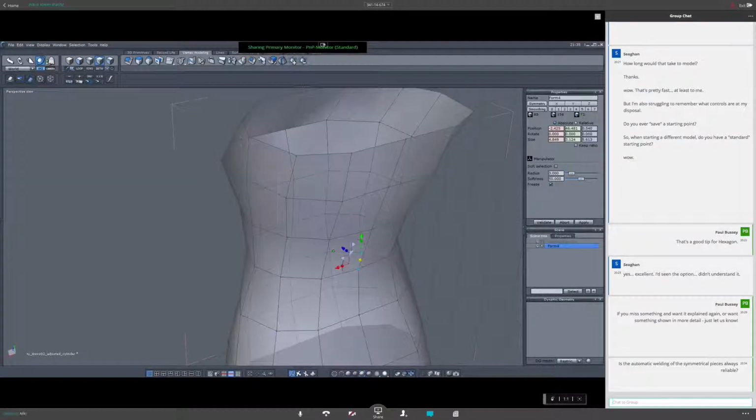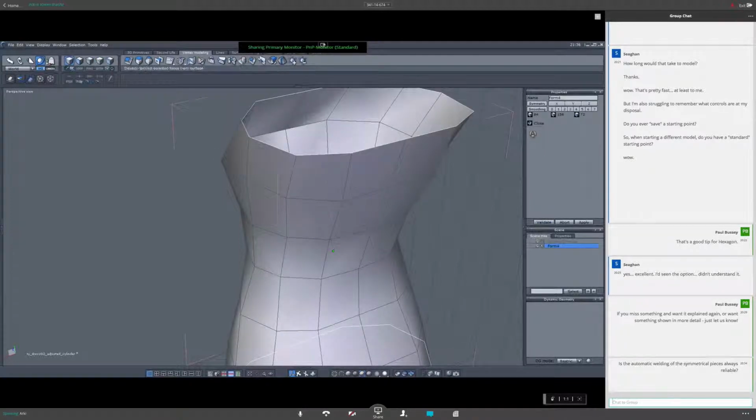What I'm doing now is I'm selecting the points. These are 2 points, but so close together that at this distance they appear to be 1. I've now selected 2 of them by using the rectangular selection and dragging it over these 2, and then I'm doing this manual operation, weld points. So it should have welded them. Now let's see. Yeah, it did.